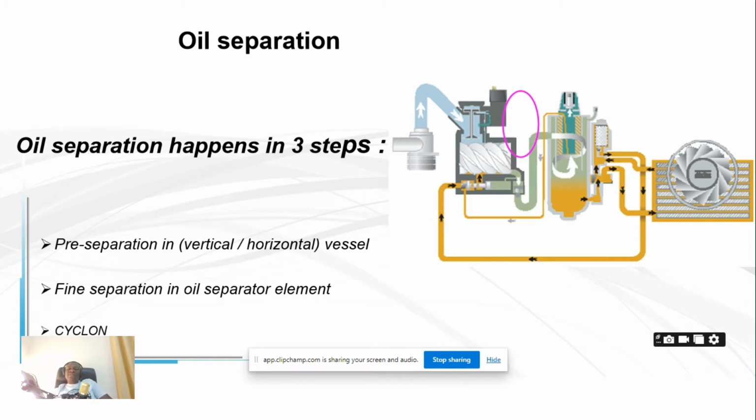And while it's going, this oil separator, the yellow thing you're seeing here, will now remove that oil. It should remove it almost up to 100%. A little will now settle down here. That little that settled down here is what will be sucked through this scavenge line back to the system. Now this is a capillary tube, so the suction pressure it receives here helps it to suck it back.